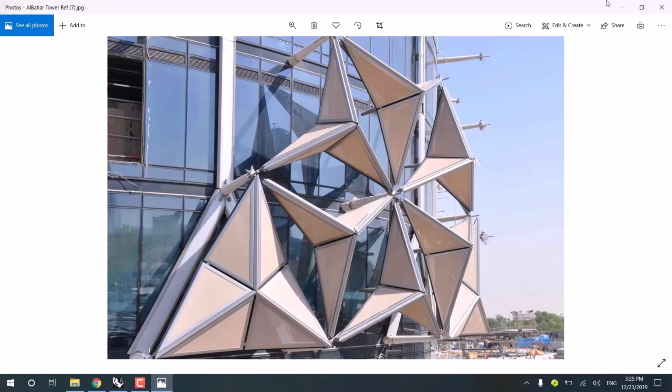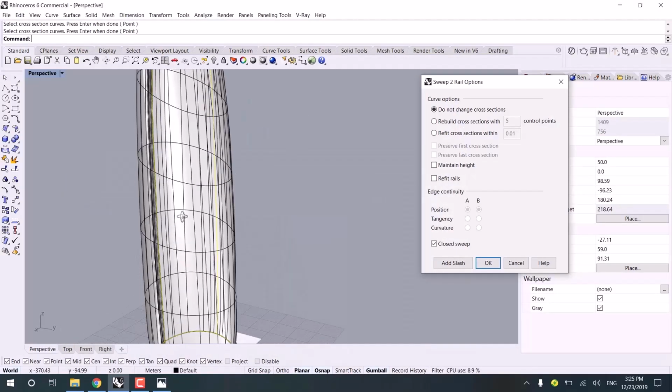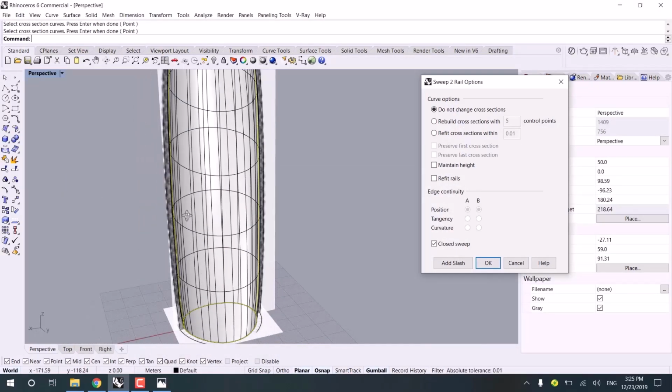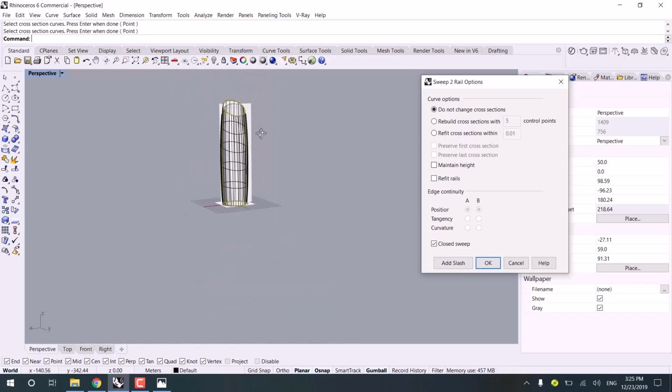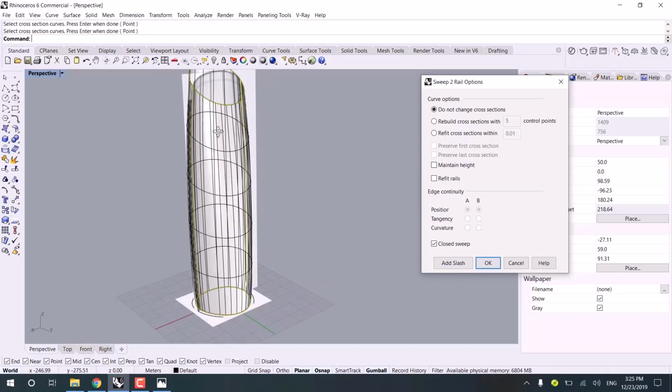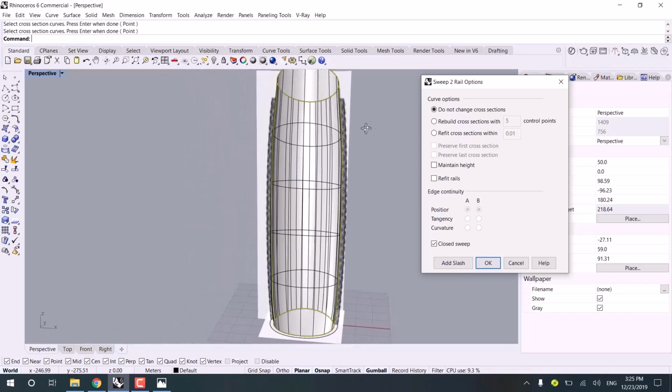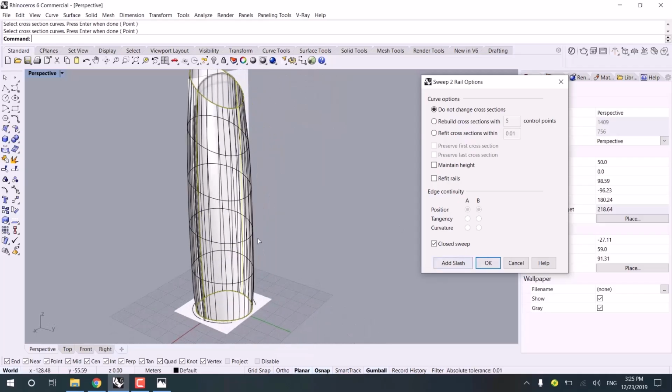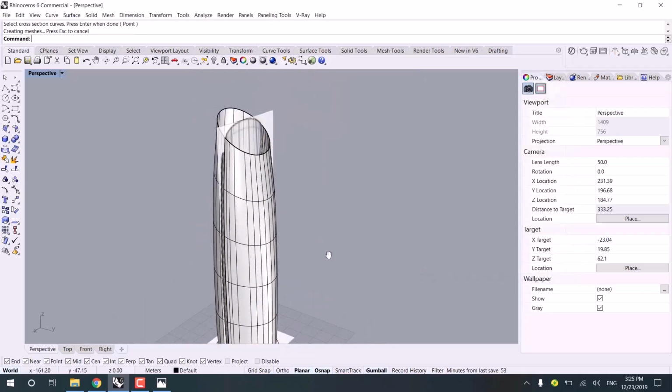In the next level, if we want to use these iso curves as the floors, we have to add a slash here to make these floors flat. But since we are going to use the contour command, we'll leave this part and we press OK.